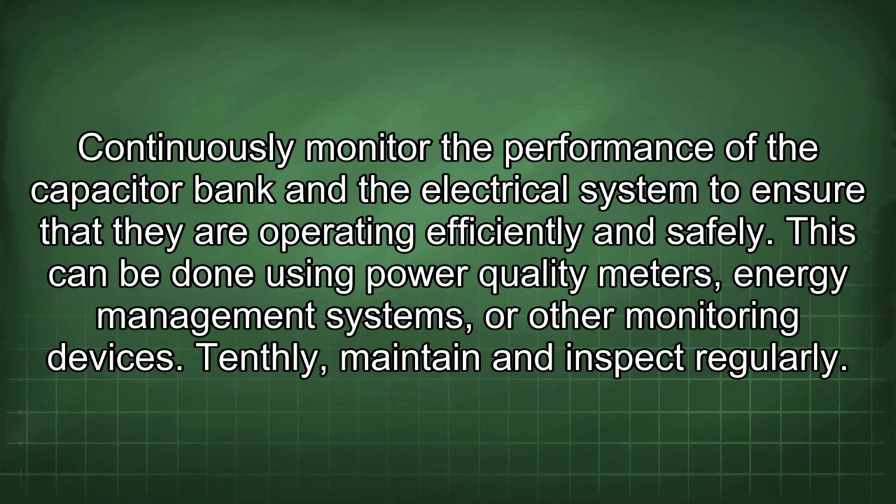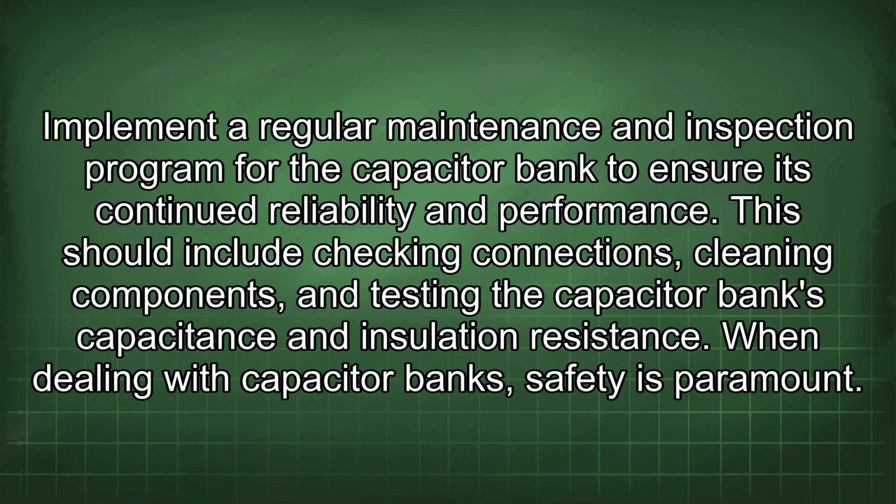Tenthly, maintain and inspect regularly. Implement a regular maintenance and inspection program for the capacitor bank to ensure its continued reliability and performance. This should include checking connections, cleaning components, and testing the capacitor bank's capacitance and insulation resistance.